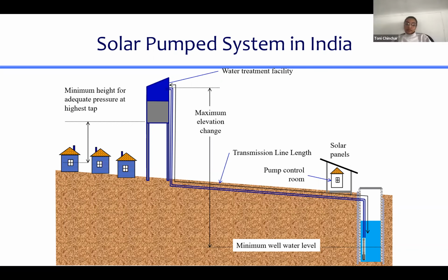So say the last part again. It would seem that I just am still confused in regards to the pressure of a bigger pipe, just because I thought there was more area, so more water would be able to fill up the area, meaning more of a force needed to push it up. So you're exactly right. The force on the bottom of the pipe is greater, but the pressure is the same. And it's the pressure that the pump has to overcome.